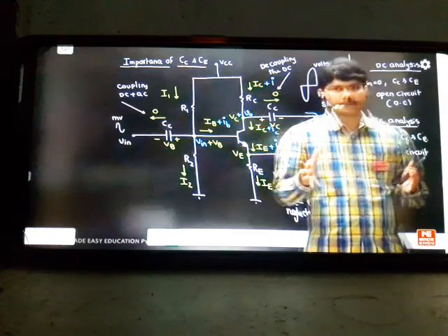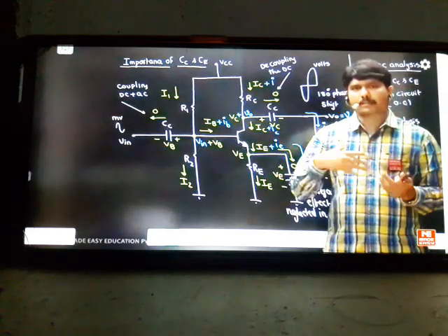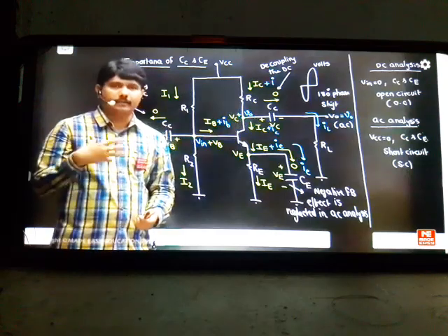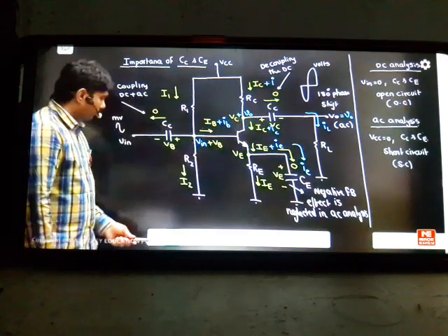DC wise, we already created the power. Just when AC enters, it is getting superimposed and it is getting amplified. But at the final stage, we don't want DC, we want AC. That's why we kept once again a capacitor to block the DC and it will give the AC output. I think this is the beauty of the concept called capacitors.